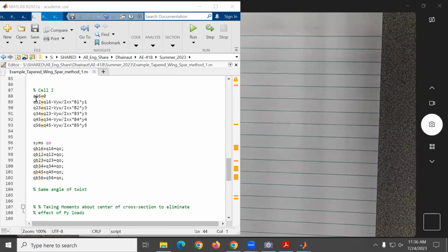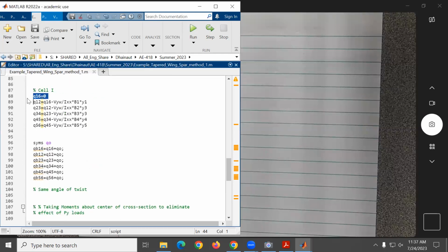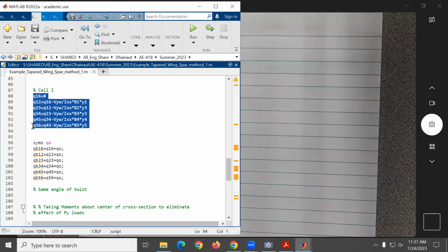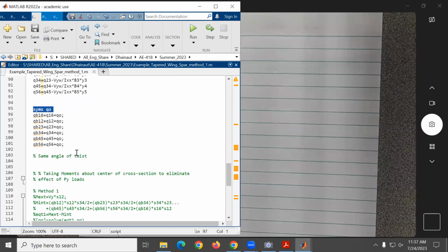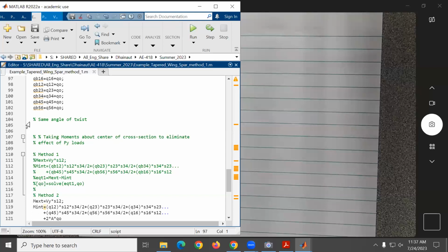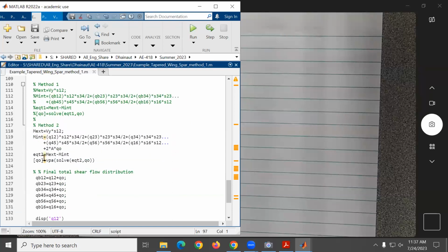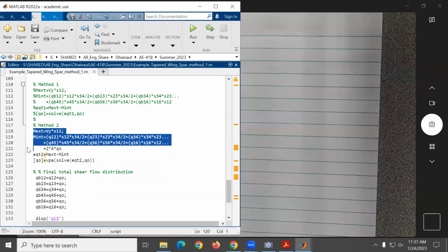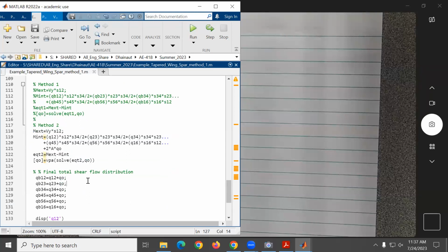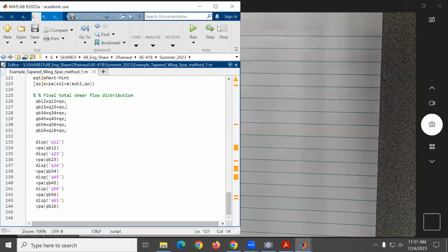And when we have the Vy of the wings, we calculate the shear flows in the cells. Yeah, making the cut. Then we need to add the Q sub naught over here after making the cut. This is now the same angle of twist because this one is statically determined. Correct? All right. So I substituted here with this equation, the moment external, internal, and basically I got this equation over here. Okay. So basically I got now the values,